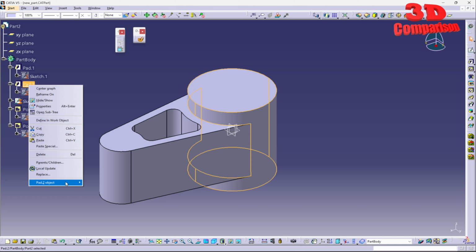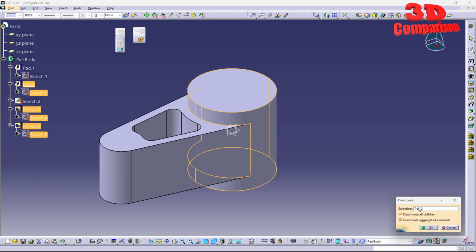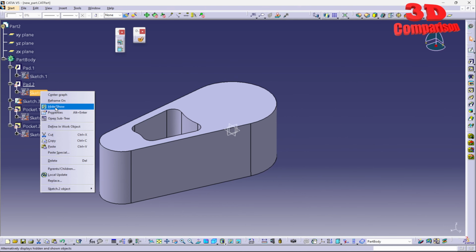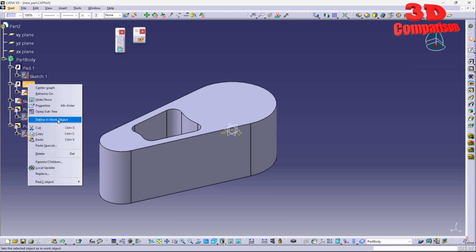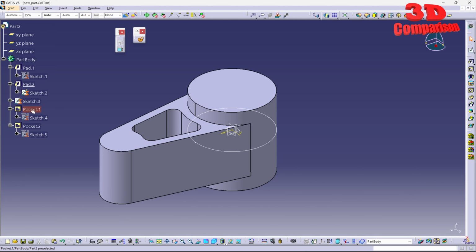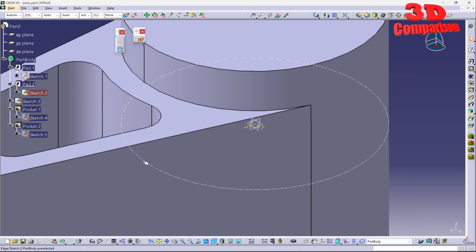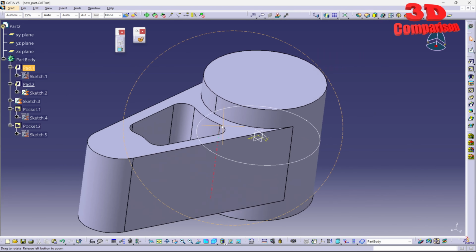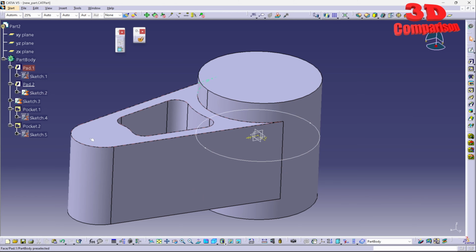If I also deactivate this, and I want to deactivate all the children over here, this will be the sketch. If I hide that, I also need to enable this. So let me activate that one and only deactivate the pockets, but this is the current state. We see this sketch, since this was created with a circle, will have that vertex over here and one over there. And those will actually create that problem with the internal topology of the mesh by adding that additional segment.